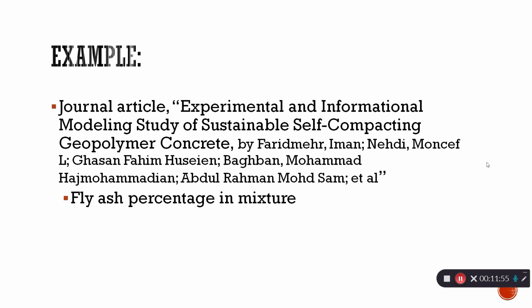At room temperature, fly ash had a slower setting time than other binders. When there was a high volume of fly ash in the concrete specimens, the specimens displayed distributed cracks with a brittle failure. The fly ash percentage mix of 30% revealed fewer microcracks, micropores, and non-reactive particles than the mixtures with 50 or 70%. The mixtures with more than 30% fly ash had a lower compressive strength.